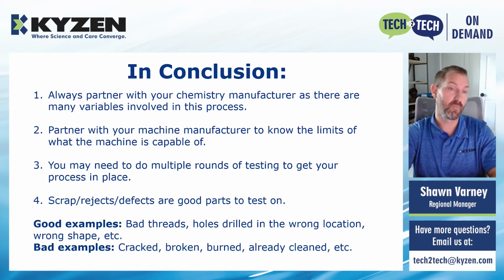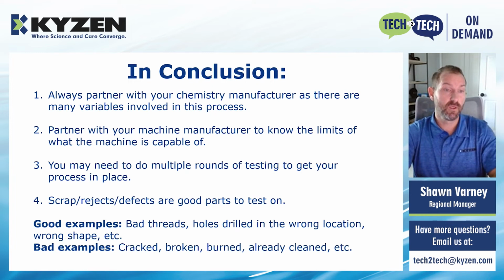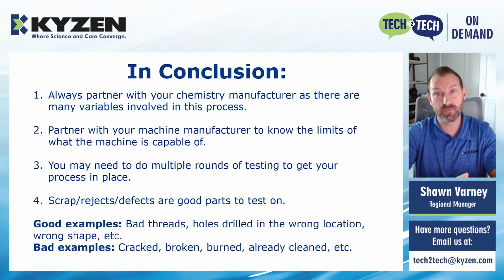Number two, partner with your machine manufacturer to know the limits of what the machine is capable of, meaning that you could have a heater that doesn't get hot enough or isn't big enough. You might need to add another one or upgrade the heater to get where you want to be temperature-wise. Number three, you may need to do multiple rounds of testing to get your processes in place. And that's completely fine. That's completely normal.